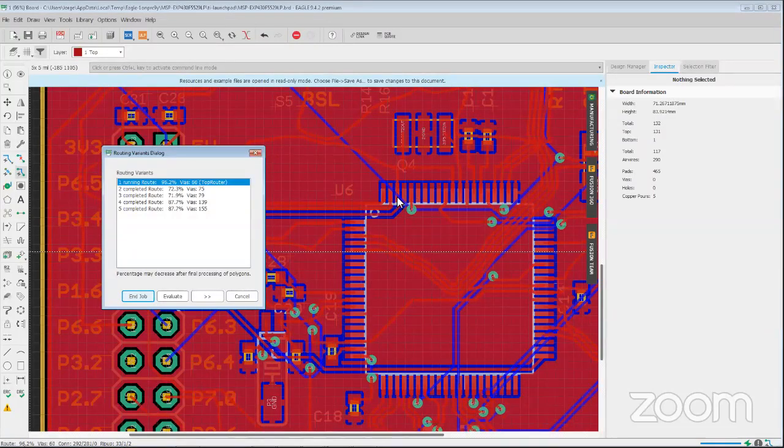I don't think we said what topological means. I'll let you give that a shot. So basically, topological means it's not grid-based. The first autorouters would basically take the work area, break it up into a grid, and all the traces would follow along the grid. A topological router isn't limited to a grid. Hence, it can make weird and more natural looking shapes. Yeah, so it's like trying to follow a contour-ish type of...